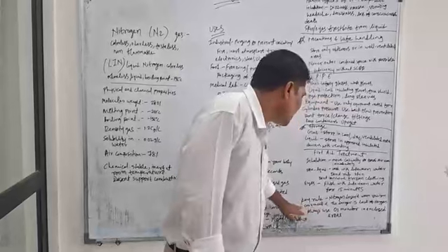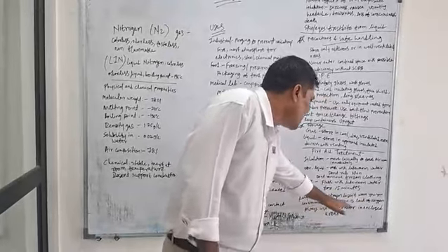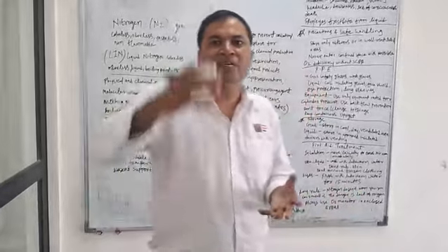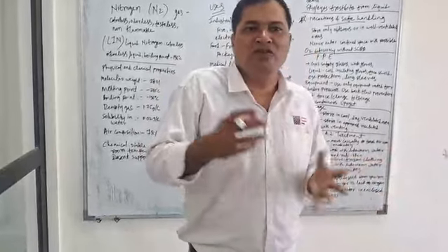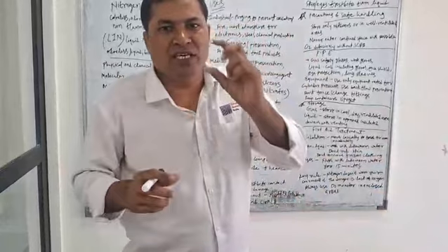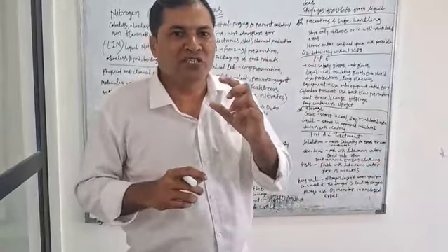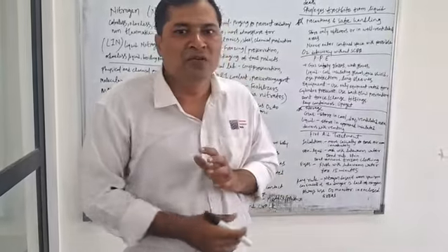The key rule is very important: nitrogen doesn't warn you, you can't smell it. The danger is the lack of oxygen, the deficiency of oxygen. So if you are going inside, always go with oxygen meters and oxygen detectors, check the level of oxygen, and then go inside.